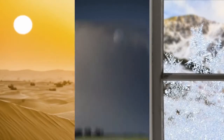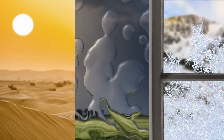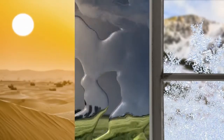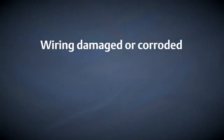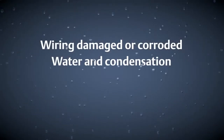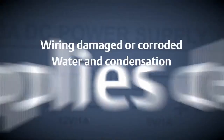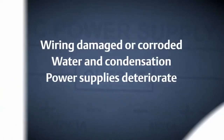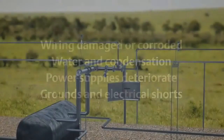Over the life of your plant, these critical components of your loop infrastructure are subjected to a variety of environmental and human stresses that can put the reliability of your 4 to 20 milliamp control loop at risk. What are some of these risks? Wires can become damaged or corroded. Water and condensation can find its way into housings and conduit. Power supplies can deteriorate and become unstable. Grounds and electrical shorts can inadvertently be introduced to the loop.